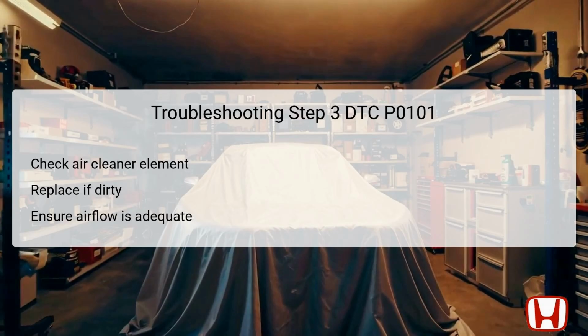A dirty air cleaner can obstruct airflow, leading to inaccurate readings from the MAF sensor. If the air cleaner element appears dirty, replacing it is necessary as it ensures optimal airflow to the engine, which is vital for performance. A clean air cleaner allows the MAF sensor to work correctly by measuring the right amount of air entering the engine.